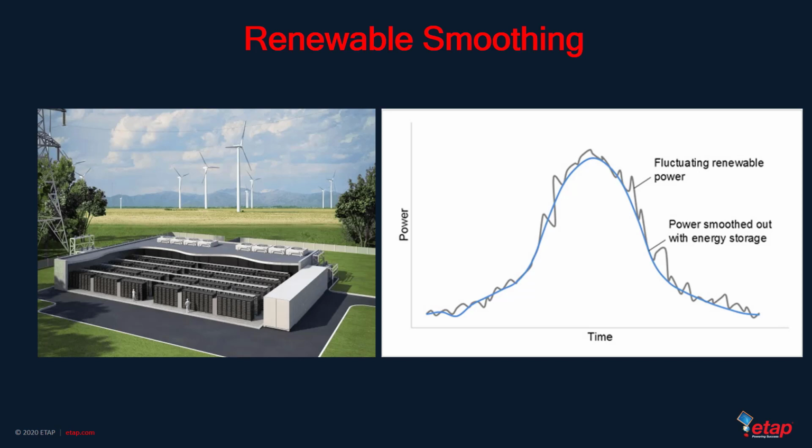Intermittent renewables are challenging because they disrupt the conventional methods for planning the daily operation of the electric grid. Their power fluctuates over multiple time horizons, forcing the grid operator to adjust its day ahead, hour ahead, and real-time operating procedures. So again, if you take an example of solar panels, solar energy is inherently only available during daylight hours, so the grid operator must adjust the day-ahead plan to include generators that can quickly adjust their power output to compensate for the rise and fall in solar generation.